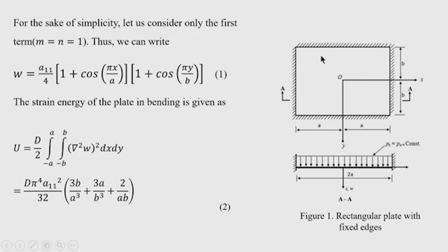You can obtain it using Levy's method by several steps, superimposing the results of the deflection due to edge moment as well as the deflection of the simply supported plate with the uniformly distributed load, and then imposing the condition that the slope will be 0 for a certain value of edge moment. Then you can substitute this edge moment in the expression, and you can find the solution for the plate which has all the edges clamped.